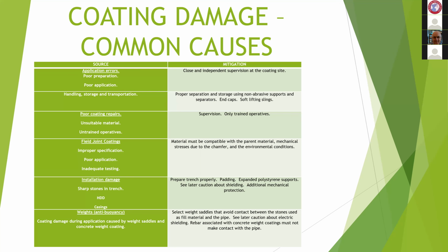It means that pipeline designers have to be really aware of the high risks associated with stray currents on pipelines, even during construction, not just afterwards. There are many incidences where this has been a problem. So you have to think, well, how do we get around that? Well, the truth is, if there's no coating defect, you won't get any corrosion.